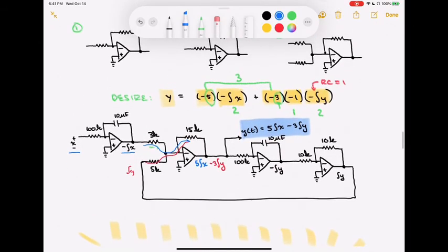So just a very simple set of operations. Same sort of idea every single time. If you have a differential equation, convert it to an integral equation, and break it up so that you can identify integration, scaling, and summing, all with that constraint of having a negative sign on it, and then just start laying down your block pieces and determine components as you go along.